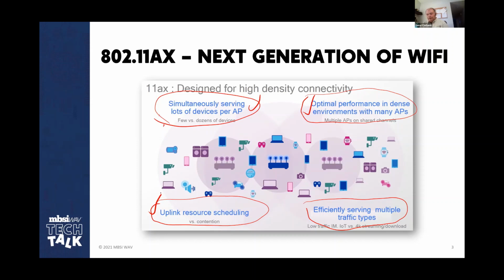So we're going to move. 802.11ax is going to take us towards the point where we can more efficiently schedule the air by having the Wi-Fi clients issue a bandwidth request. The access point will then schedule that communication. So now we no longer have to worry about contention. We don't have to have the pseudo-random backoffs and other things that are part of the contention-based mechanism. We can work toward having more Wi-Fi clients connected to an access point.